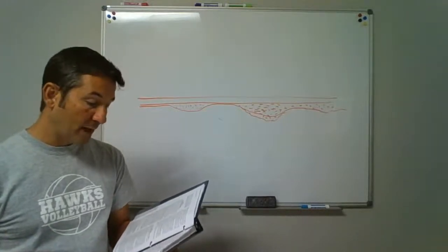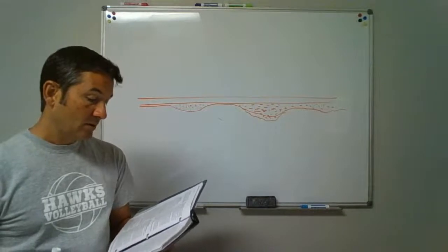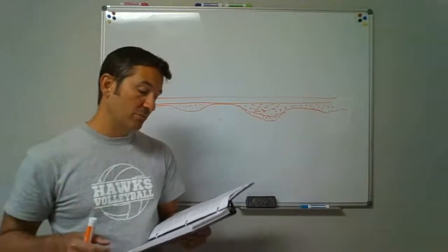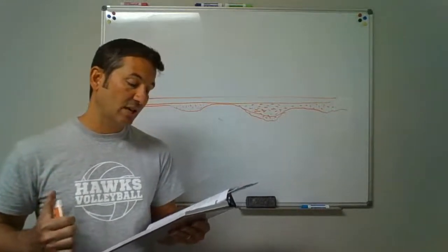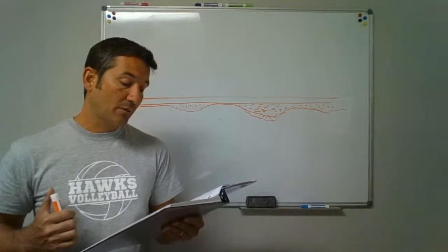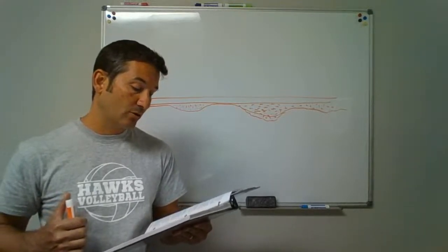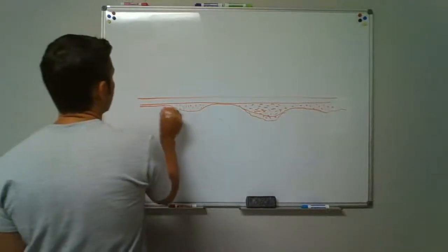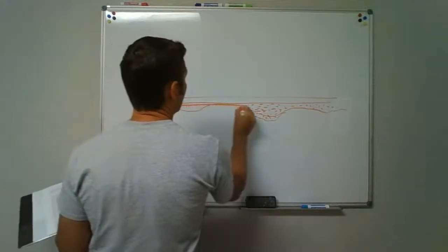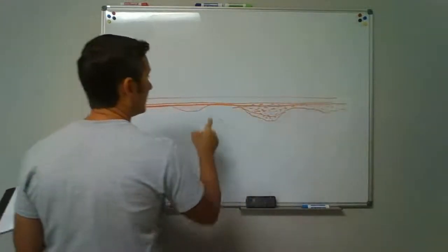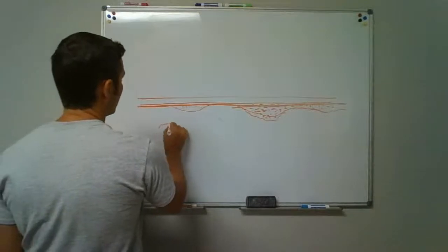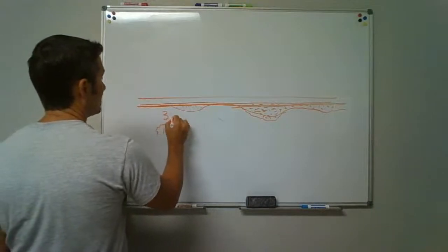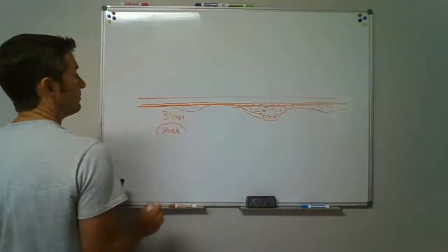Let's see. If you're backfilling, once again, loose earth free from rocks, broken concrete, and frozen chunks should be placed in the trench in 6-inch layers and tamped in place until the crown of the pipe is covered by 12 inches of tamped earth. Okay. So it's saying you've got a nice bed now, a nice, even, level supporting ditch. If you had some rock under here, you've got at least 3 inches minimum of good dirt built up on top of there.